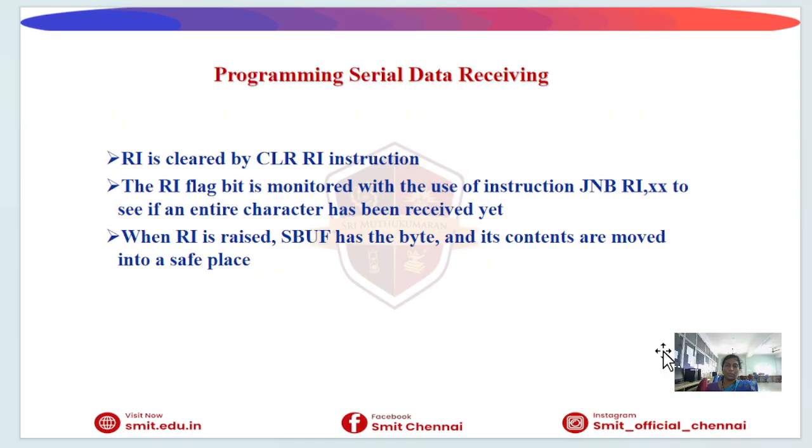Next one is programming serial data receiving. This is how the 8051 receives the serial data. The data is received through the receive pin. Before the receiving starts, the RI flag is cleared. The RI stands for the receive interrupt flag.